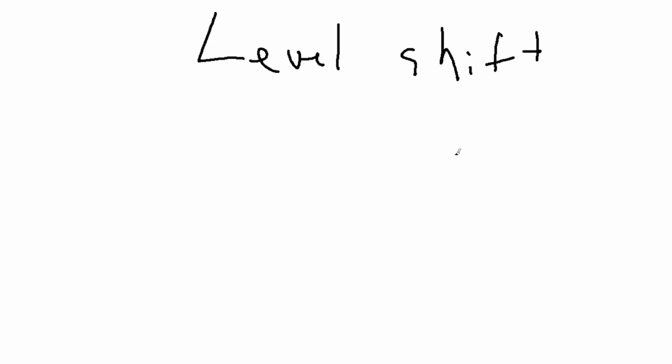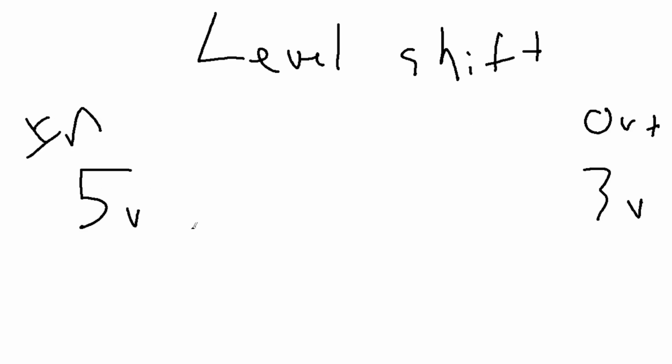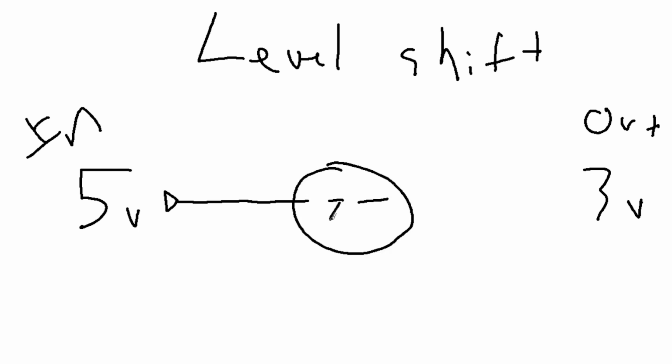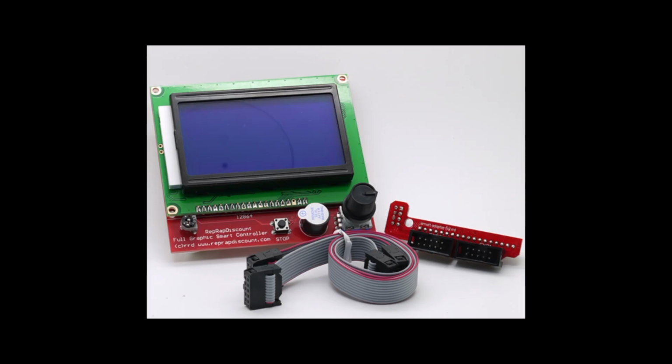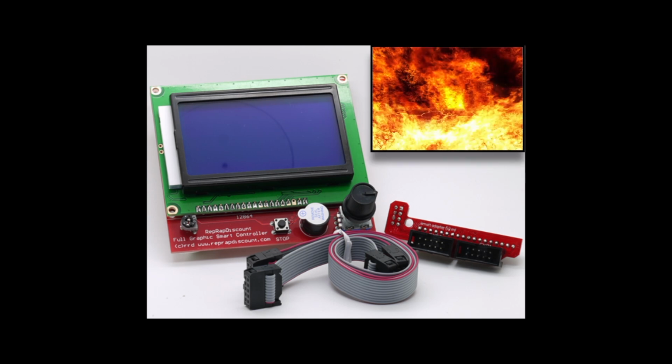Now, these STM32 chips have an advantage that some of the other chips from different manufacturers don't, in that they're 5-volt tolerant on a lot of the pins, but some of them are not. So it's possible that there are just level shifters on all of the ins and outs. Those are basic questions we would need answered if we were to even know what it is we're allowed to plug into the board and out of the board, what kind of signal levels we're going to be getting. Because it's a compatibility issue, and it could be a matter as simple as, oh, that thing's not going to work with those signals, or it could be as dangerous as, no, you're going to blow up that thing, or you're going to blow up your microprocessor.